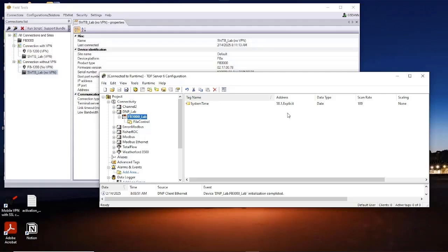As you probably know, DNP3 is a relatively new protocol being used in the oil and gas market, so there's not a lot of understanding, I would say, of it. It was actually new to me as well when I got into it, and I've been in the oil and gas industry for over 30 years. But understanding how to address parameters from the device, we'd want to do it with a more easy to recognize name versus having to track down what this address is. So the goal of this proof of concept was to effectively get a namespace built within the OPC server.